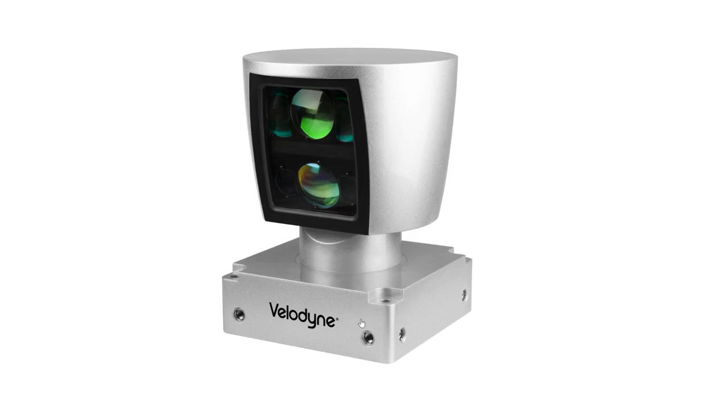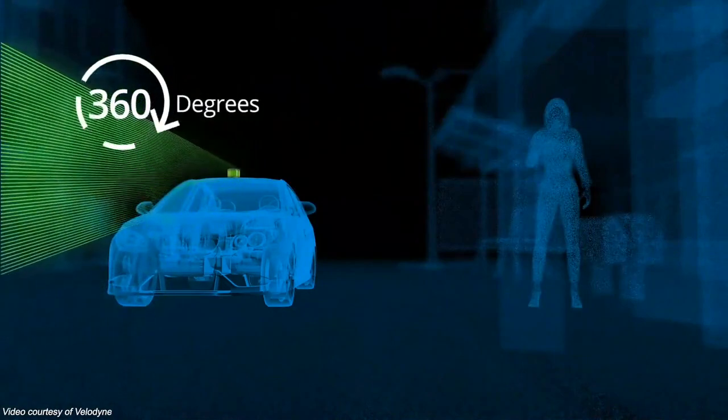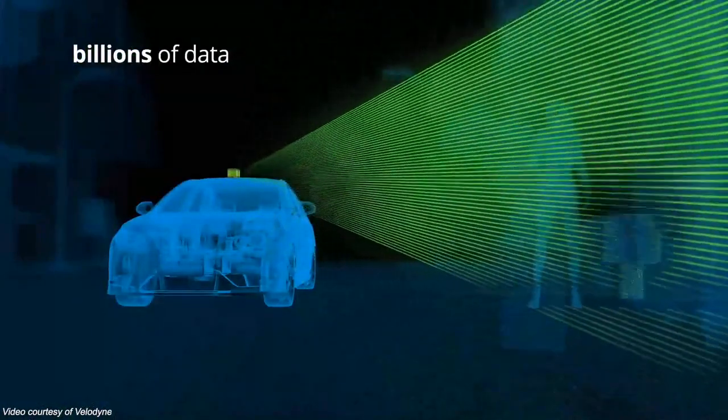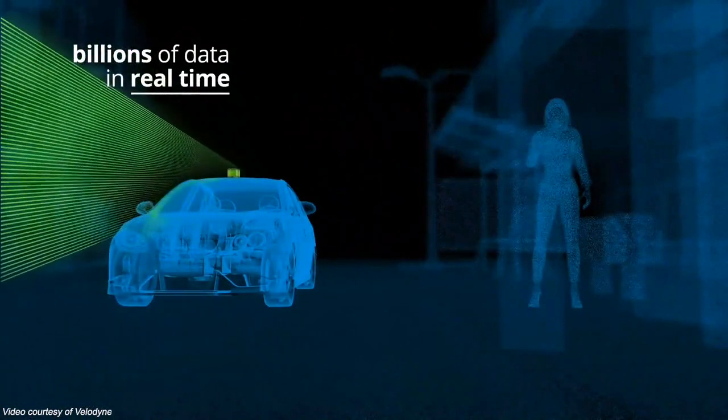This is an example of a 3D scanning LiDAR that currently is used in many automated vehicle development projects. You see the emitter and receiver apertures. Actually, in the last few years there has been a rapid increase in the number of LiDAR sensors with 3D scanning functionality. Here you can see the conceptual representation of how a 64-beam LiDAR from the company Velodyne can sweep the surrounding 360 degrees and produce billions of data points over time. The sensor provides millimeter measurements of the vehicle surrounding in 64 vertical layers of LiDAR measurements.